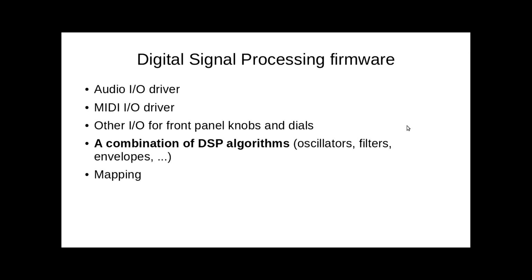So to get this thing talking, we need to develop some digital signal processing firmware that breaks apart into an audio input-output driver, a MIDI input-output driver, other input-outputs for front panel knobs and dials, and then you make any combination of digital signal processing algorithms like oscillators, filters, envelopes, and then you have to map the parameters to control it somehow, and some bookkeeping to load new presets or things.